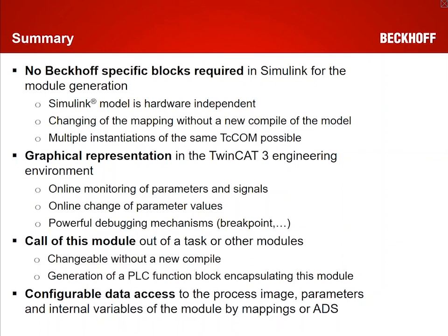And what we also have seen is that you can call Simulink models out of a task by setting the modules in a task context, or you can call the model out of other modules. In this case, we've shown using the PLC wrapper how you can call the TCCOM object out of the PLC. Of course, you can also call a TCCOM object generated out of Simulink using a C++ coded TCCOM object.